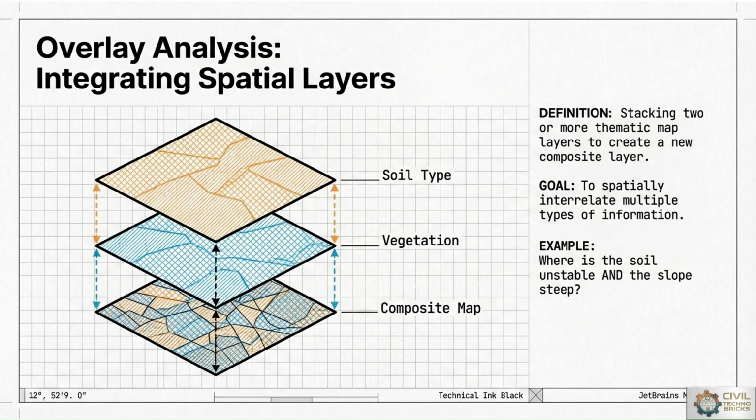Overlay analysis provides the information based on the process of stacking different thematic layers on top of each other to create new composite layers, or n number of layers. The objective is to analyze relationships between different data sets, which works by superimposing or correlating the layers such as land use, soil, slope, characteristics, and many more. Common methods for overlay analysis include union of layers, intersection of two layers, or weighted overlay analysis.